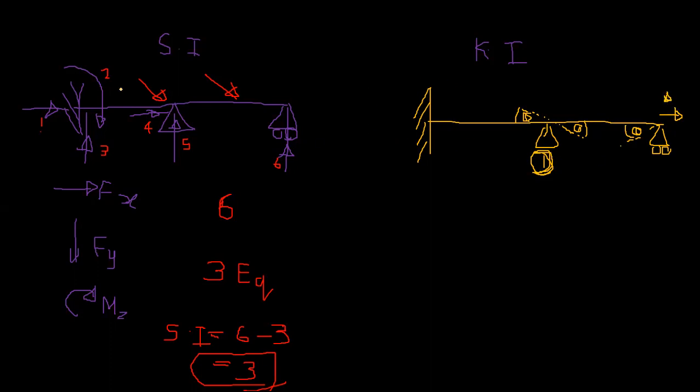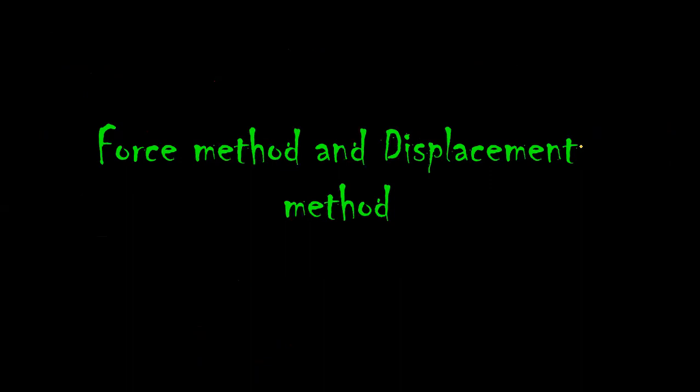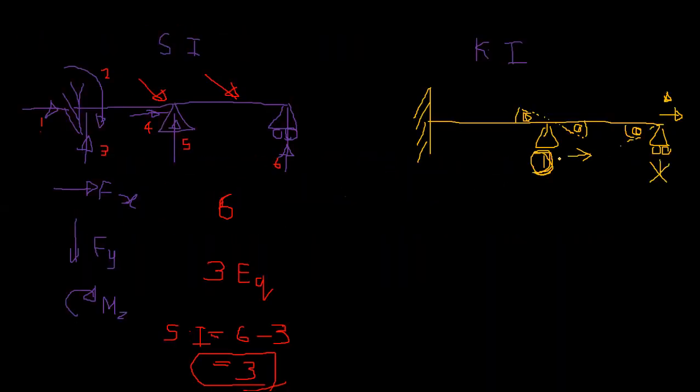From these three displacements which can occur, it can restrain downward translations. Here it will restrain downward and positive x directions as well. So here no translations and no rotations, two gone, one is remaining.